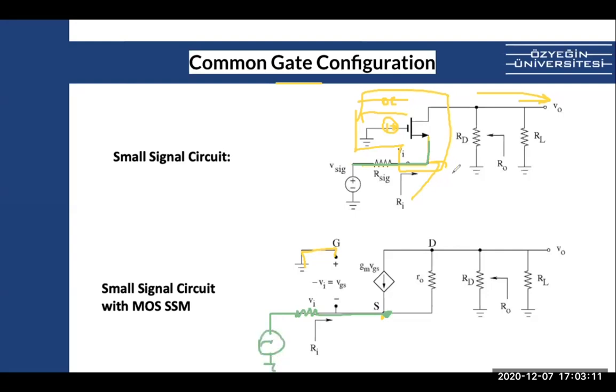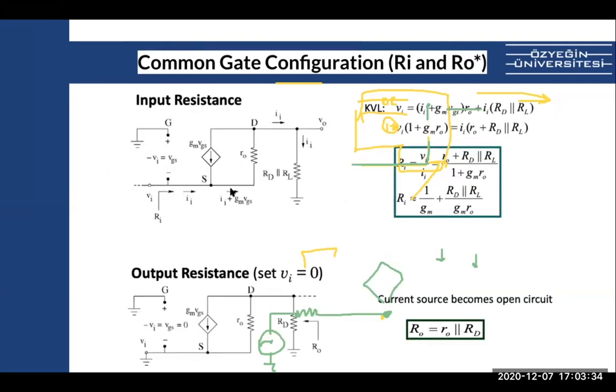And now you are doing the source and drain, the same logic you do it. Okay, there is the drain, and then the rest of the circuit. And then we have to solve for the output impedance, input impedance, and gain for the circuit.